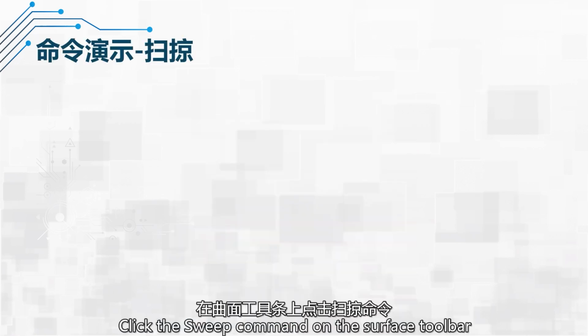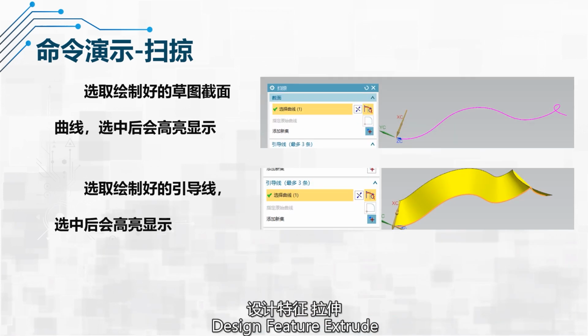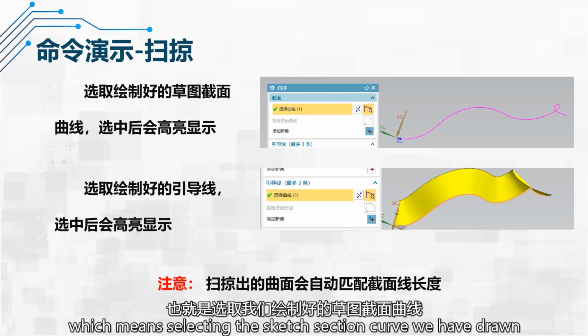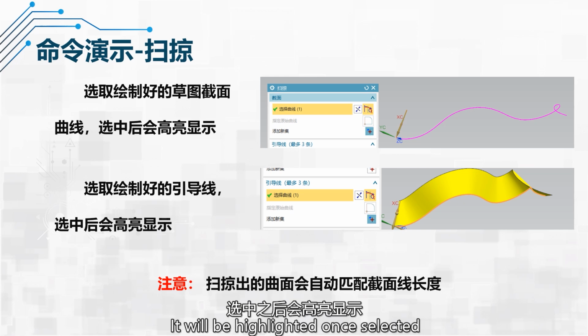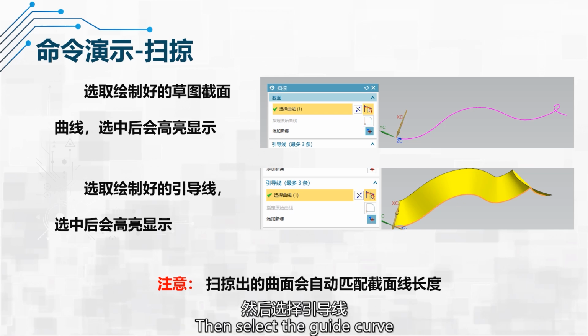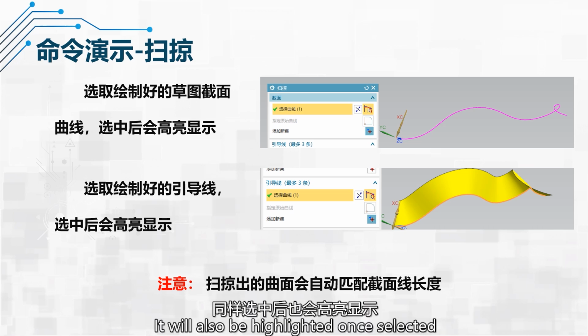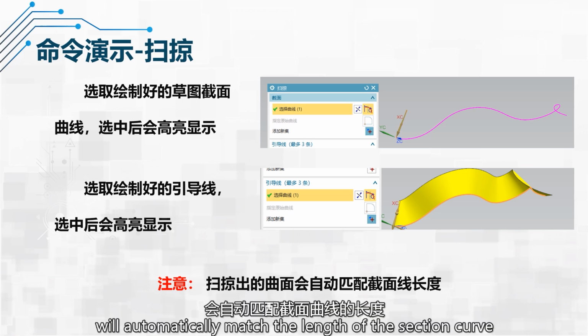Click the Sweep command on the Surface toolbar or go to the drop-down menu Insert, Design Feature, Sweep. First, the Sweep dialog box. Select the section and choose the curve, which means selecting the sketch section curve we have drawn. It will be highlighted once selected. Then, select the guide curve, choosing the guide curve we have drawn. It will also be highlighted once selected. Note that the swept surface will automatically match the length of the section curve.